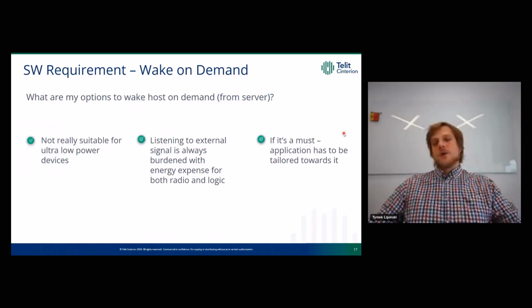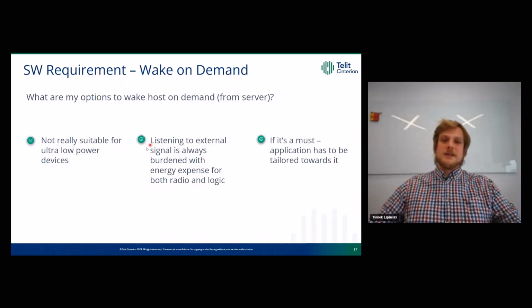Let's discuss our options to wake host on demand from server. So in my opinion, it's not really suitable for low power devices. And why is it not suitable? Well, listening and having some features active is always burdened with energy expense for both radio and logic. Why? Because radio has to listen for the paging, right? And listening for radio means that all of the DSPs and radio processing units in the module have to be active, even for a short period of time.